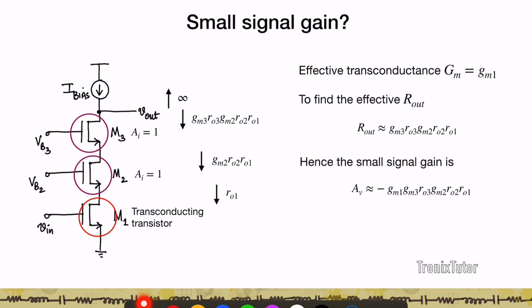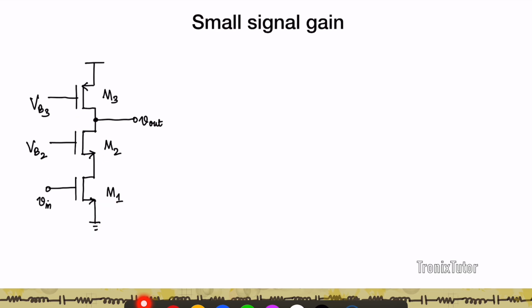the output reduces. And especially as transistors scale, as technologies scale, you begin to see that the VDD is scaling quite fast. VT isn't scaling fast enough. And so the headroom in technology is reducing, which makes it harder and harder to support these large cascode stages. So you see that in most cases, your cascode is going to be restricted to not more than 2 transistors. That is just a 2-stack cascode, if you will.